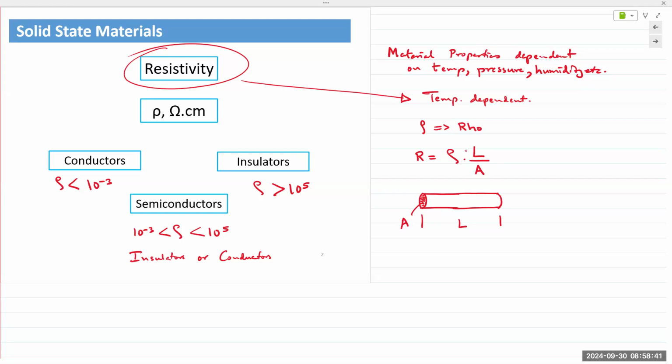Higher operating temperatures would require, well, let me put it this way. Anytime energy is transferred, which is what we are doing, electrical energy is always constantly being transferred, heat is generated. When it gets hot, material gets degraded. So the resistivity for conductors actually increases with heat. For semiconductors, it actually decreases with heat. And so that changes the operation of your circuit, especially when we are talking about micro devices, small scale, temperature affects it a lot.